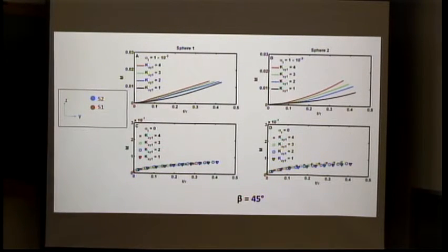So with higher anisotropy, you get more dilution. That is when considering transverse dispersion. If you don't consider transverse dispersion, you don't get any difference between the different cases. So all the dilution here is induced by transverse dispersion.